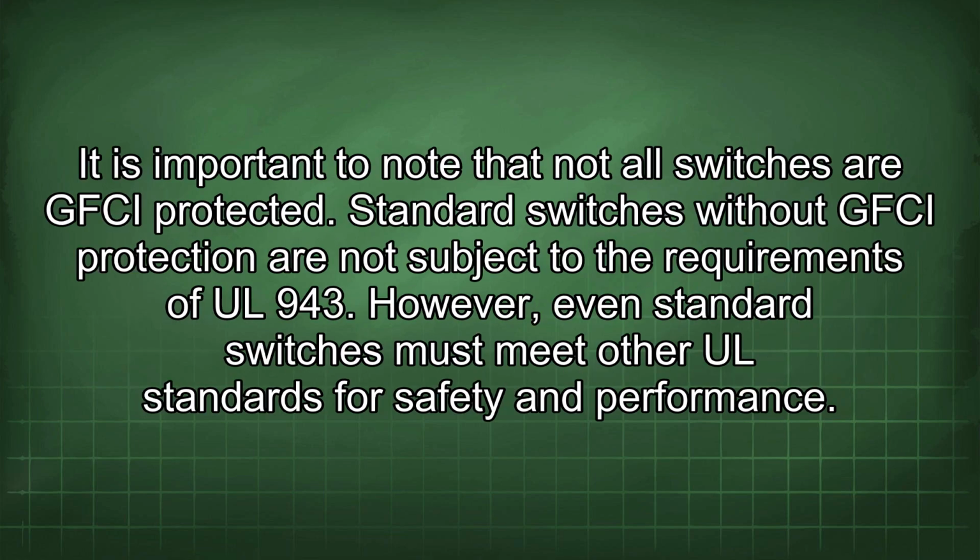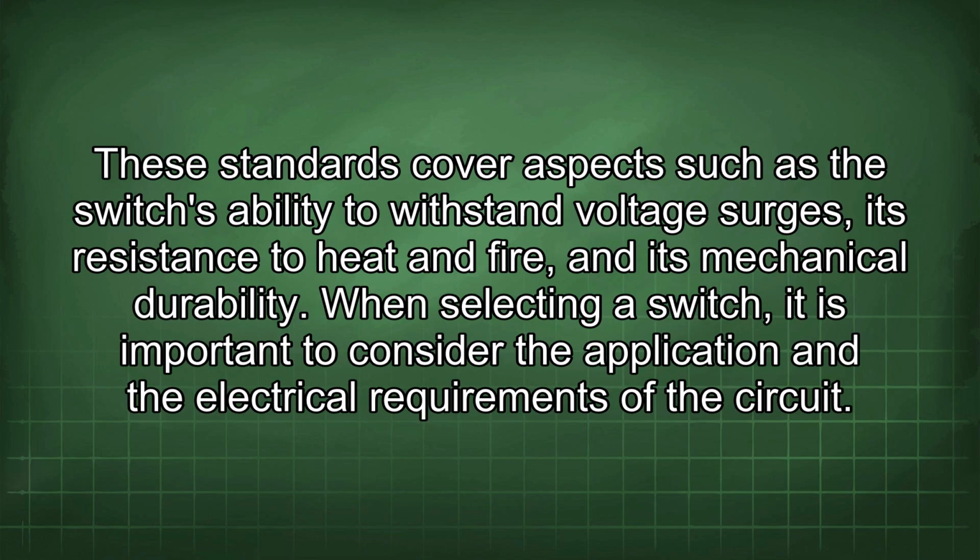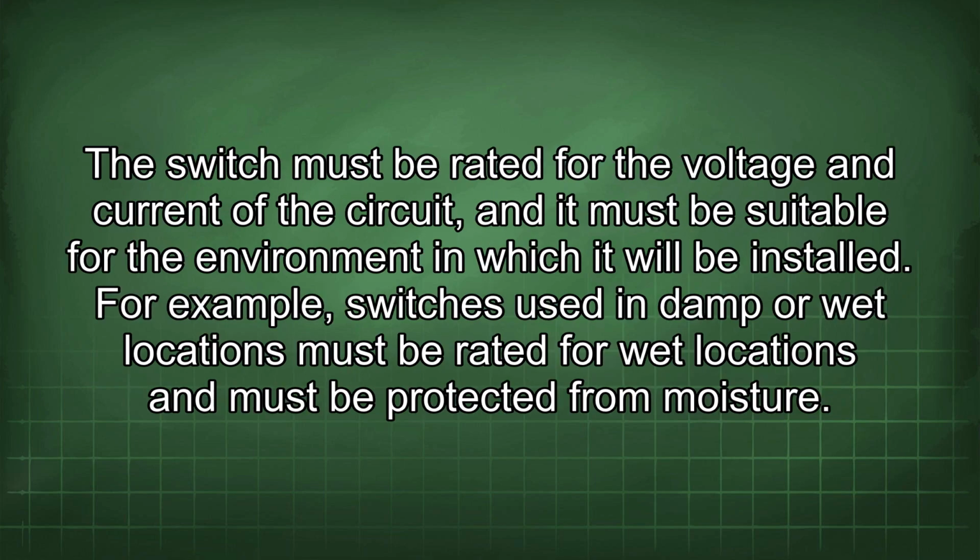It is important to note that not all switches are GFCI protected. Standard switches without GFCI protection are not subject to the requirements of UL 943. However, even standard switches must meet other UL standards for safety and performance. These standards cover aspects such as the switch's ability to withstand voltage surges, its resistance to heat and fire, and its mechanical durability. When selecting a switch, it is important to consider the application and the electrical requirements of the circuit. The switch must be rated for the voltage and current of the circuit, and it must be suitable for the environment in which it will be installed.